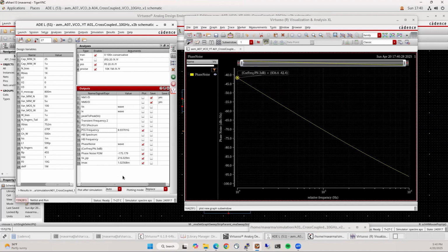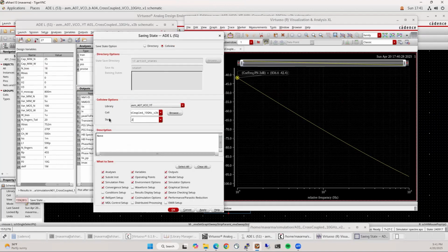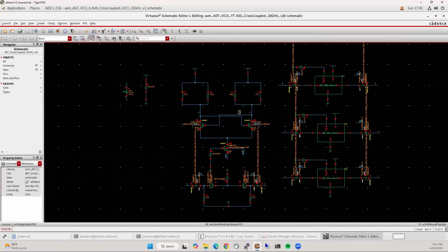I don't want to go into too much detail in this video. This is just sort of a first pass design of a VCO that has both continuous and discrete tuning. Of course, you can do a lot more from here. So let me actually just quickly save this. Right, so you can investigate, for example, we looked at that in the previous video, which was the tail current effects video, which transistors were contributing more to the phase noise, and then try to see if we can minimize those. There are many techniques for phase noise reduction of oscillators, so that probably requires a separate video.